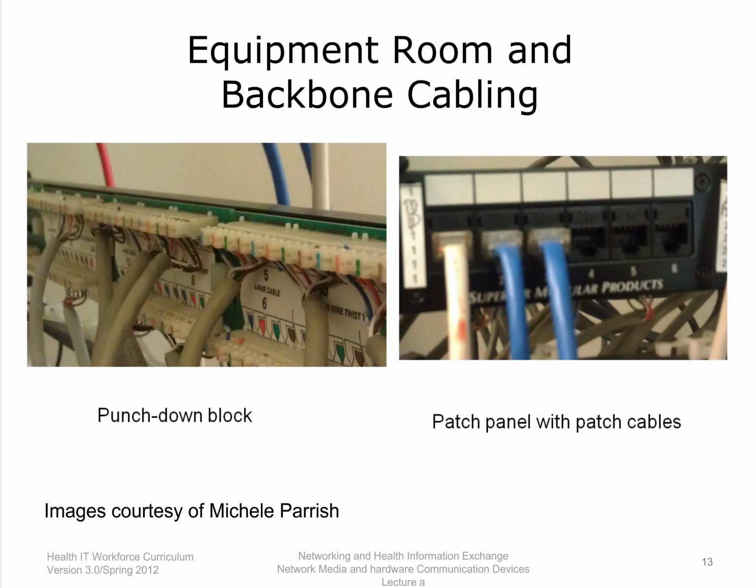Backbone cabling includes the vertical connection between floors, risers, cables between an equipment room and building cable entrance facilities, and cables between buildings, interbuilding. The cables between floors and between equipment rooms are typically TP or fiber, with the cables between buildings being fiber.